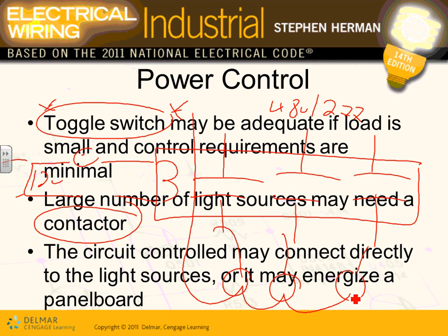Here's what they do, Adam, on bigger systems. Say I'm going to put 10 lamps here, 10 lamps here, 10 lamps here. They're big enough with the size and the watts. Here's where they use this for a bigger parking lot. They have a contactor like the one we use in the motor, except they're called lighting contactors, made to work with lights, high intensity discharge lights. These are called lighting contactors.